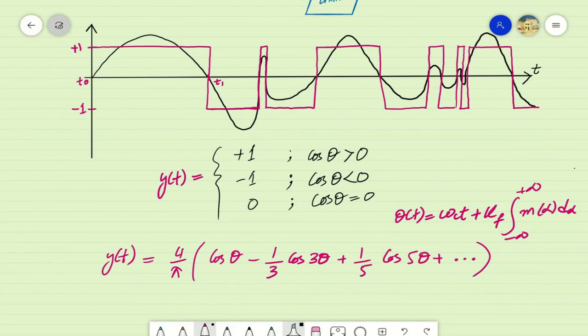So if we substitute the value of theta in equation number 3 here, we can represent the case where a time varying peak amplitude variant of the frequency modulated signal is received at the input and fed to the hard limiter on the receiver; the output signal will be represented by this equation number 3.